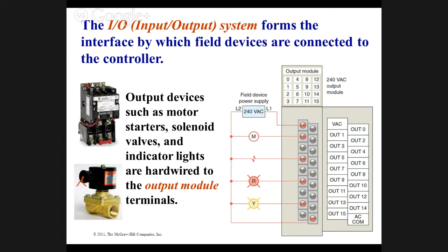One thing about outputs on a PLC is those little cards have an amp rating. So you must make sure that, like you see on the left, it shows a big NEMA style contactor. On most small PLCs, that big contactor would pull too much current. It would work for a little while, but it would eventually burn up. So you have to pay attention. The outputs on these PLCs, they don't handle a lot. You can buy them that handle more. Most people put a relay on it if it has to handle high current. But anyway, there's an example of an output. Pretty good so far?